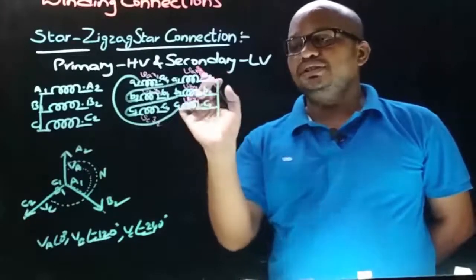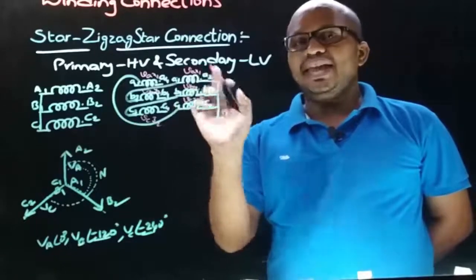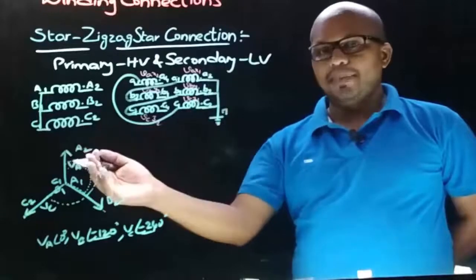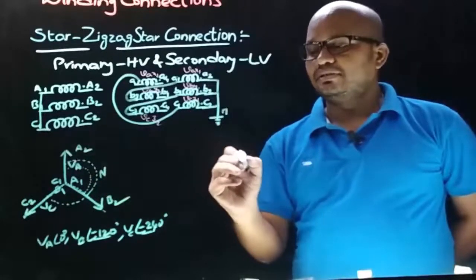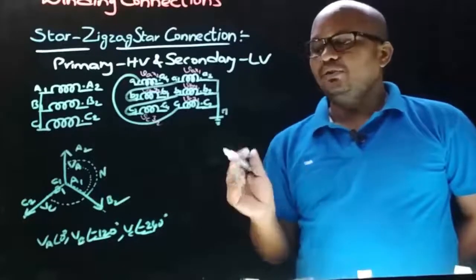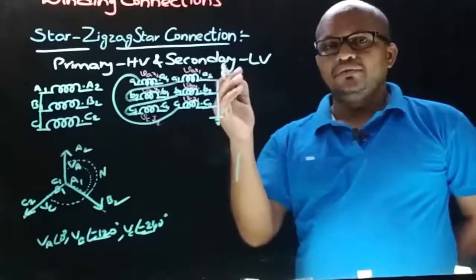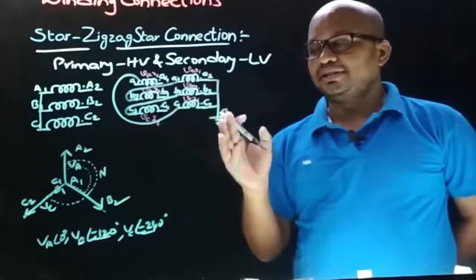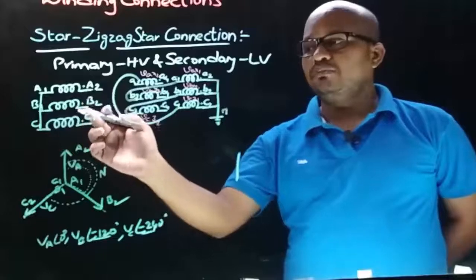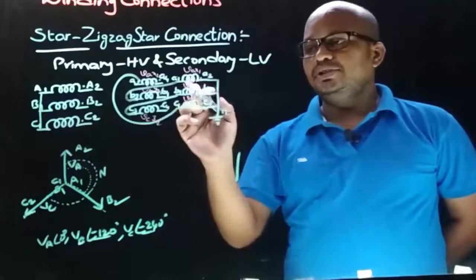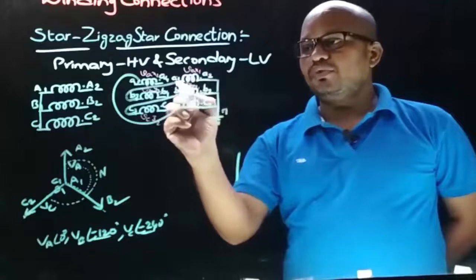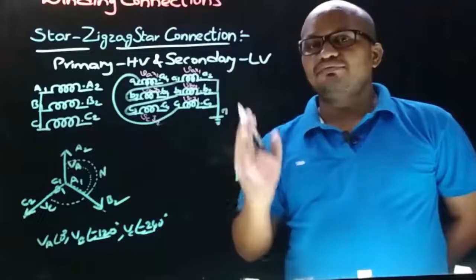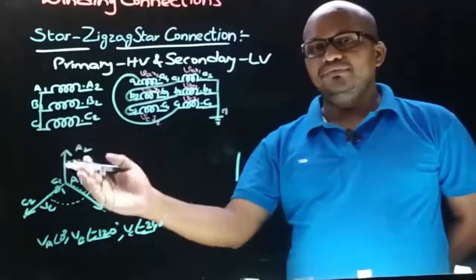Now first let's draw the secondary side VA X1 phasor. Therefore let's draw the secondary side VA X1 phasor parallel to the primary side VA phasor like this. And now we need to decide the direction of the secondary side VA X1 phasor, and the direction depends on the connection we took on the primary side and secondary side. By observing, on the primary side connections are taken from the dot end, and coming to the secondary side, connections are taken from the non-dot end. Therefore the direction of the secondary side VA X1 phasor will be opposite to the primary side VA phasor.